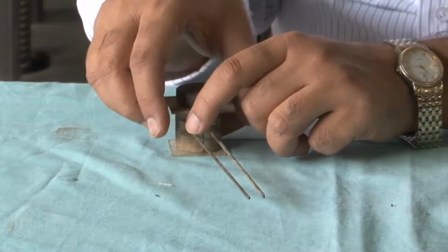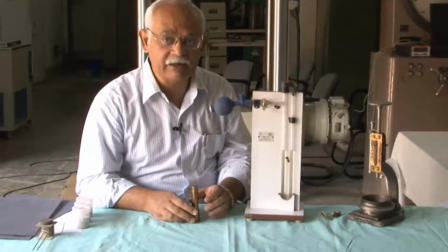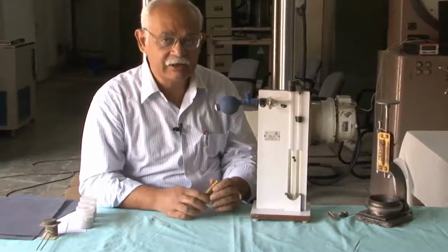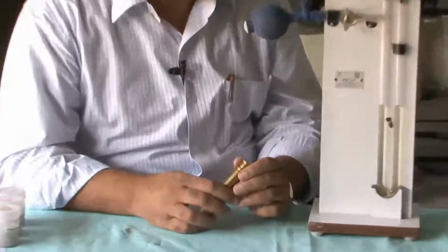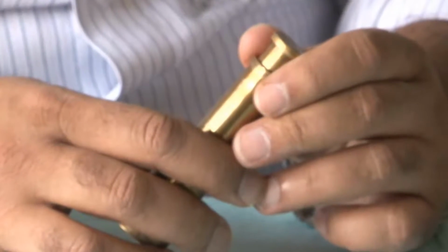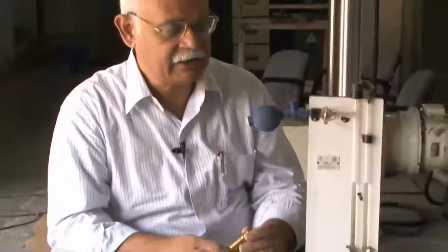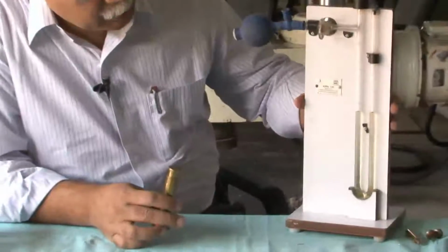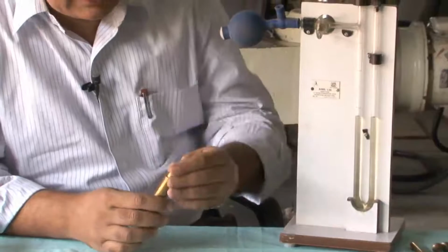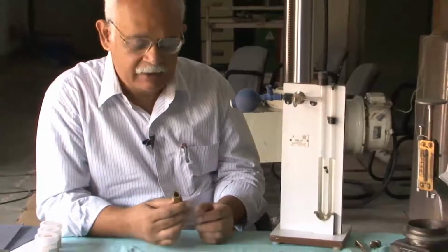That is how we measure the soundness of cement. This here is the Blaine's apparatus to determine the fineness of cement. Fineness of cement is expressed in terms of centimeter square per gram or meter square per kilogram, and is determined using the Blaine's apparatus, where we take a cement sample in this tube in a certain